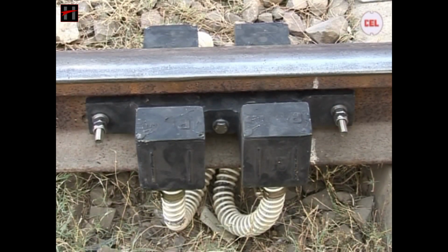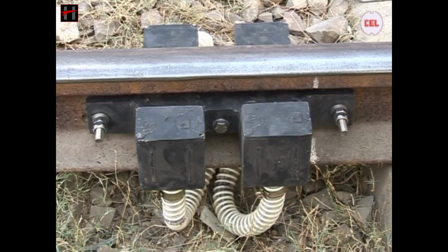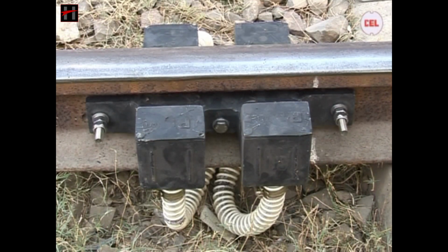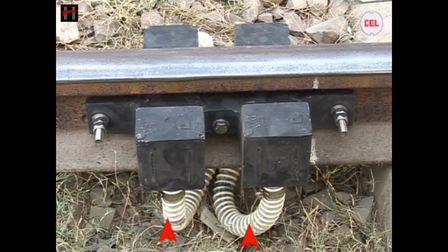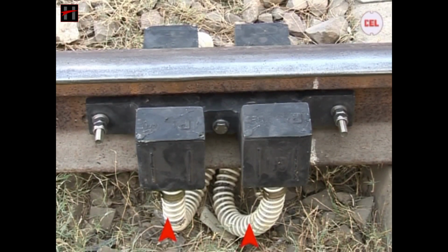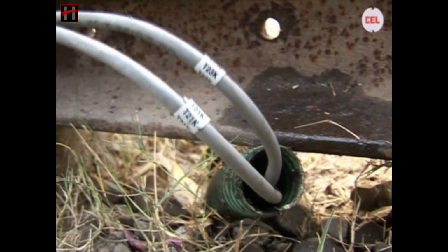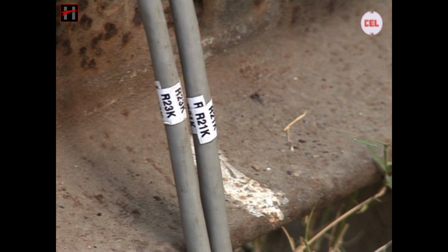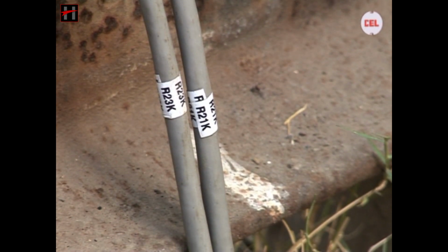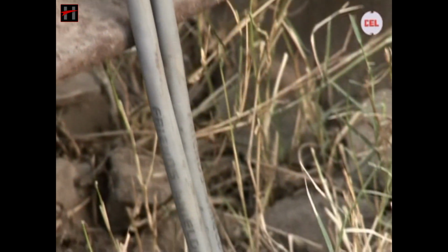Make sure to keep the hose pipe attached to the TX coil and RX coil housing in a curve and not pressed in ballast. This curve or loop will help in reducing the tension or damage of housing during vibration. Take the TX coil cables marked with 21 kHz and 23 kHz together in one HDPE pipe to the location box. Similarly, take both RX coils marked with 21 kHz and 23 kHz together in a separate HDPE pipe to the location box.